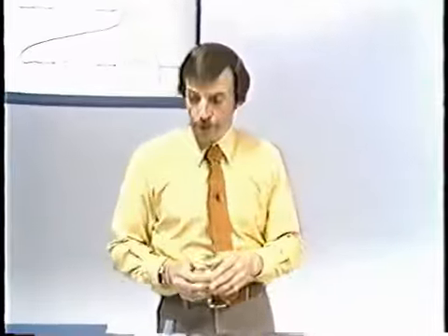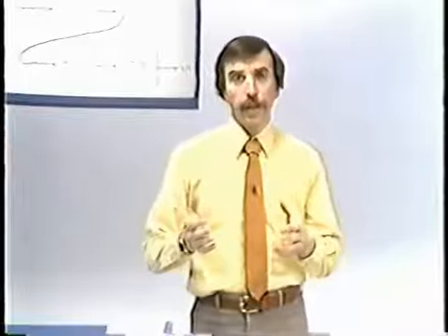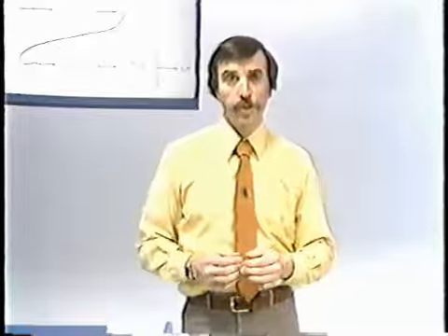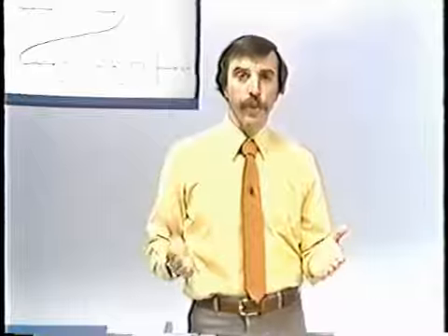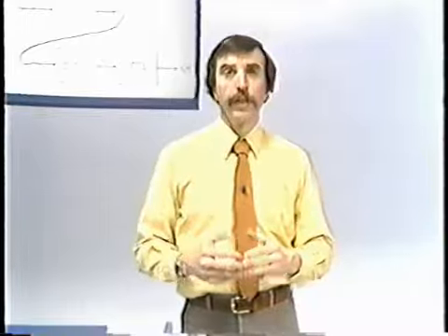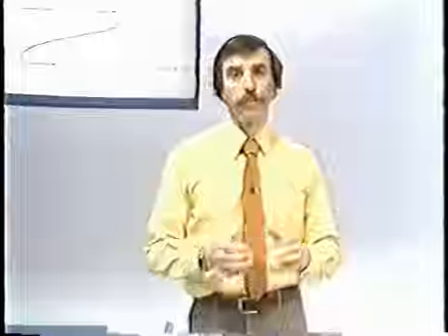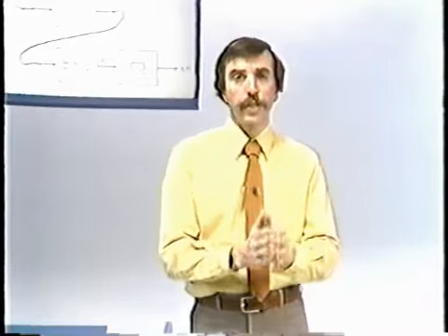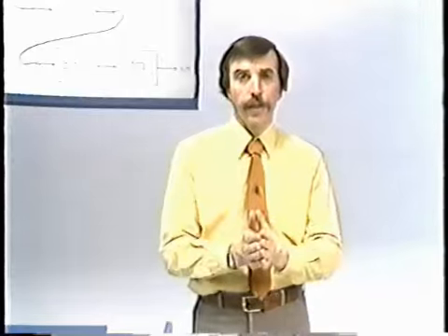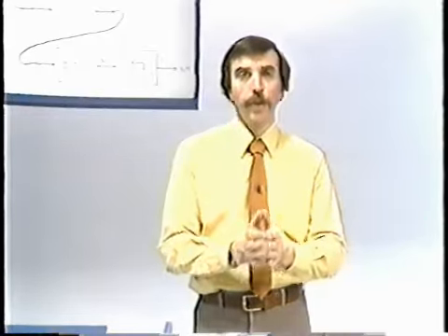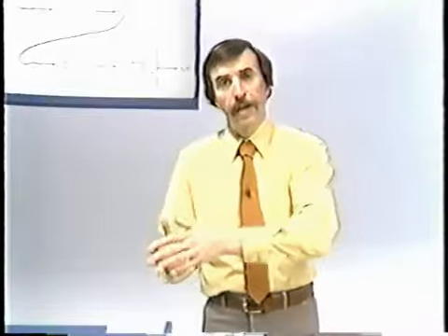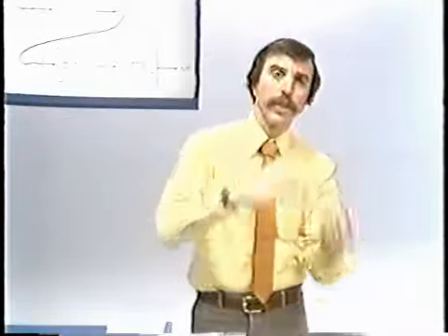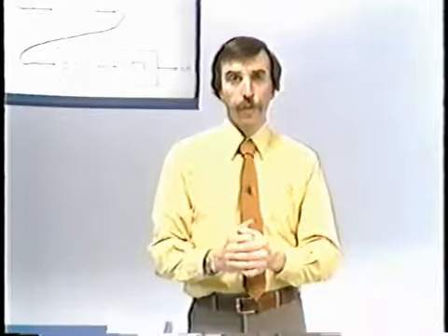Now, in the demonstration, the sampling rate that's picked for this part of the demonstration is a 20 kilohertz sampling rate. That means, based on the sampling theorem, that as long as the input frequency is below 10 kilohertz, we get no aliasing. When the input frequency goes beyond 10 kilohertz, that higher frequency is going to get aliased down into a lower frequency.